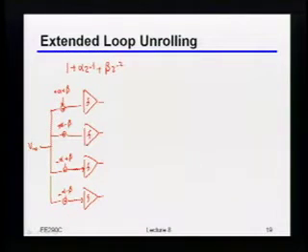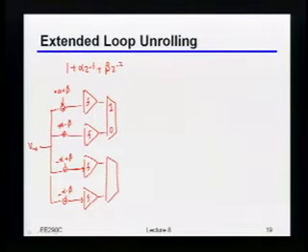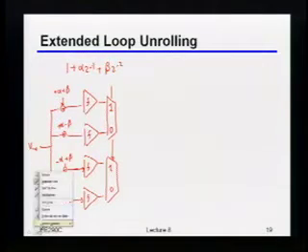Okay, so now how do I pick which one of these is the right answer? What sort of pieces of information do I need to know? Yeah, I need to know what was the previous bit and what was the bit sort of 2 clocks ago, right? So I rearranged things this way because I just wanted to make my drawing a little bit easier. As an example, in this case, based on the bit that's going to be 2 periods ago, I'm going to select, for both of these, whether I choose the upper comparator or the lower comparator.